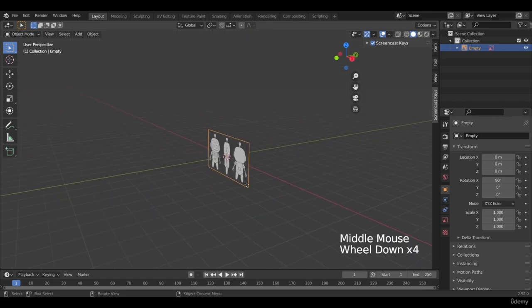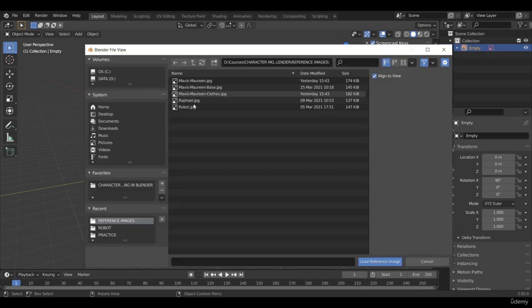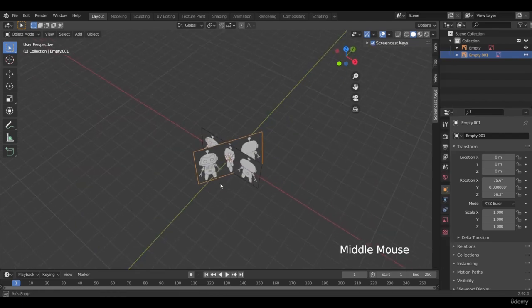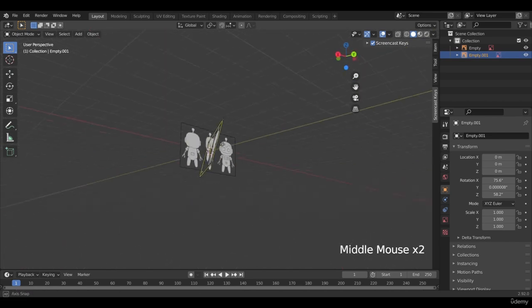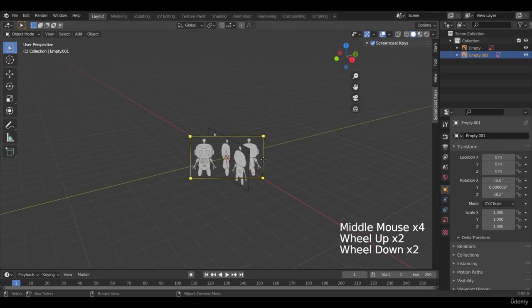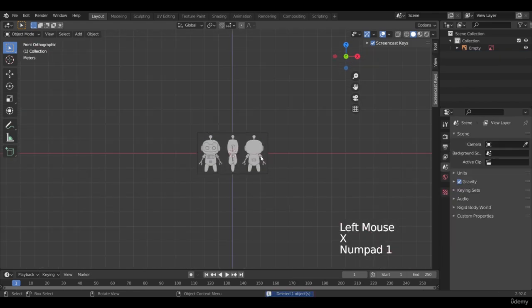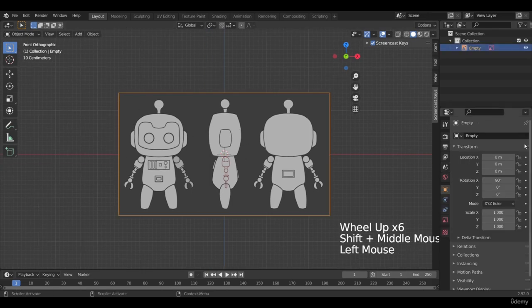If I added an image in the perspective view, like here for example, I add the same image. Look, it's not gonna be in the orthographic view that I need. It's just gonna be in a very weird position. So we don't want that. We're gonna delete that, and we're gonna go into our front view and add it from there. Once we have it, we're gonna select it and go into the properties menu.